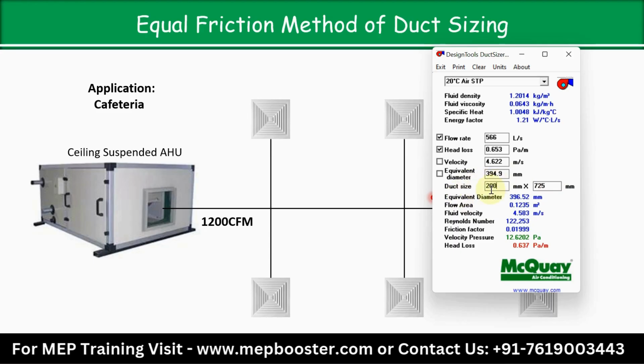So when I select 200, the condition is satisfied, but the aspect ratio is coming closer to 4, and it should always be closer to 1. That is why here I am using the height 300. When I select the height 300, the width is 450. Now when you calculate the aspect ratio, 450 by 300, you get the value 1.5. So this value is closer to 1. Clear? So better to take the height of the duct as 300 mm.